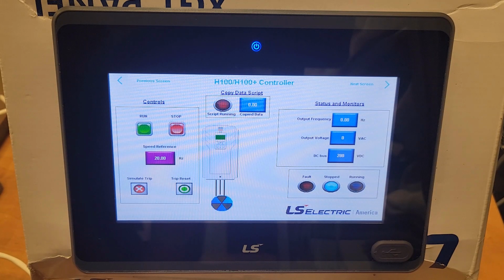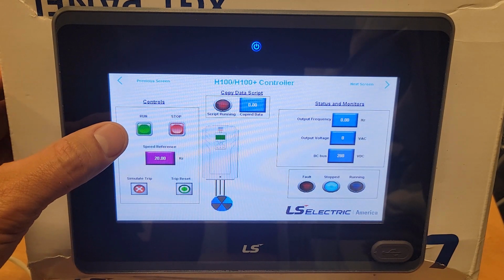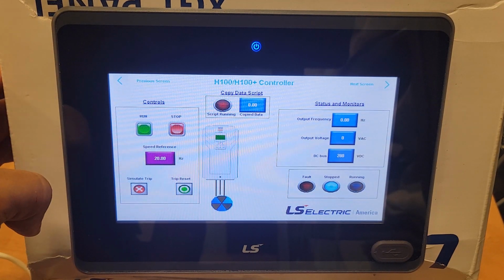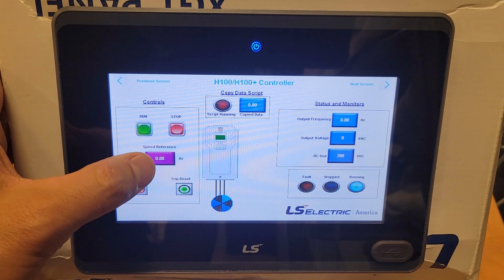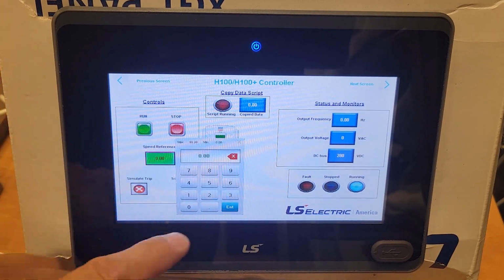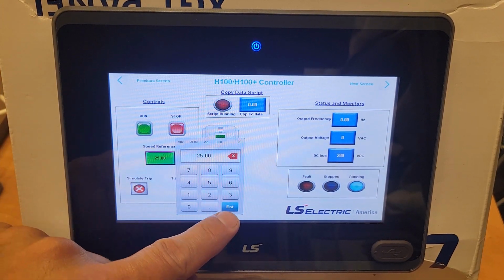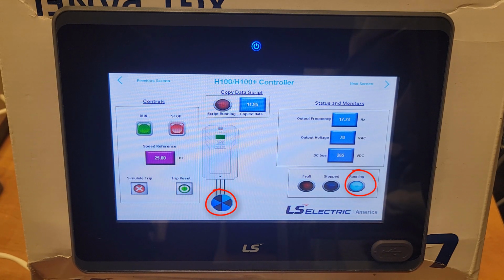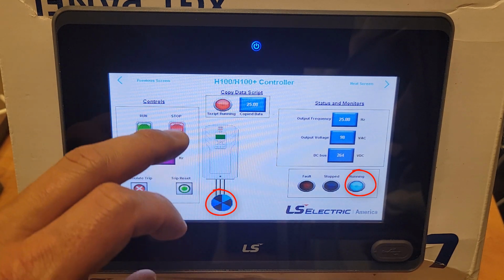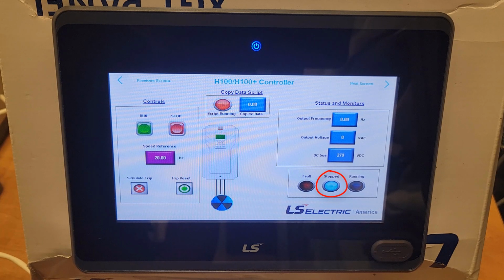If we go to the second page right here, very simple. This is your run bit, so it's going to turn on your run. Let's see, oops, I got to go to auto. There we go. So let's stop it. Show it again. I press the auto key on the drive, and I can run. This is monitoring the run status. This should be mapped to the same register, the same bit. If I stop it, it goes stop right here.